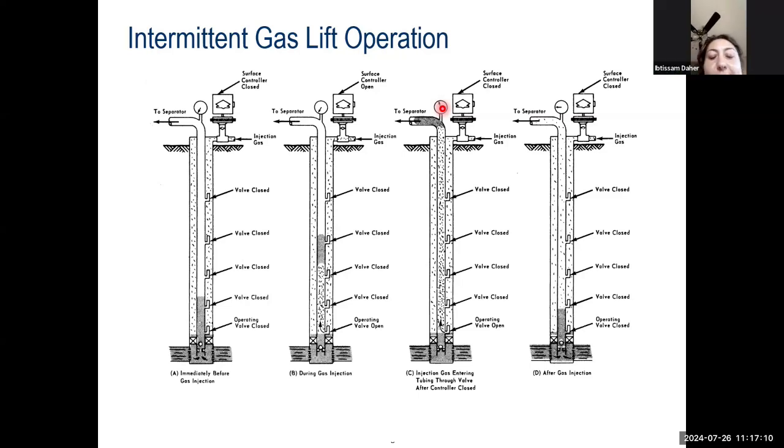I'll just have a quick question. When an oil field is all depleted, do they leave the tubing in the ground, or do they pull that up? No, so at the end of the life cycle of the well, there is something which is called plug and abandonment. What actually happens is that the responsible companies will pull all this completion out. They will cement the hole, and they will do all the remedial work on the surface so that it goes back to its original condition.